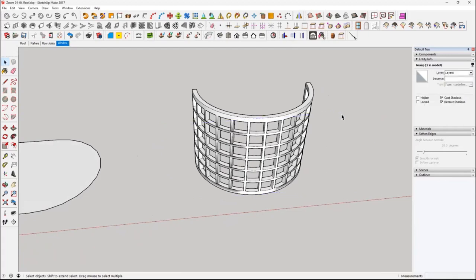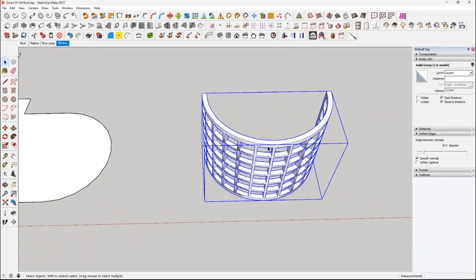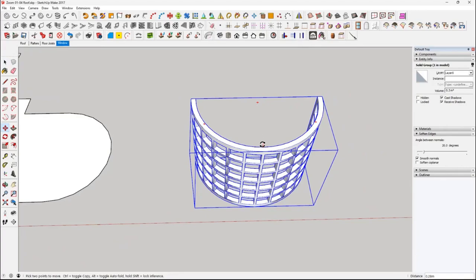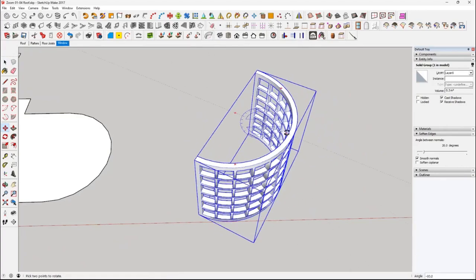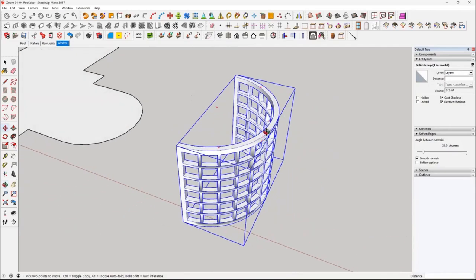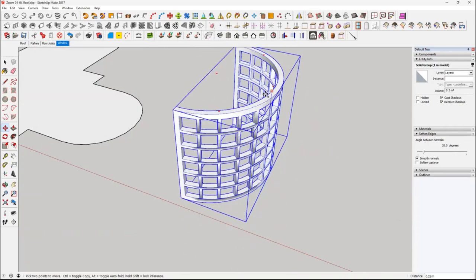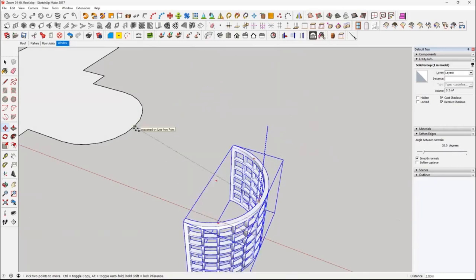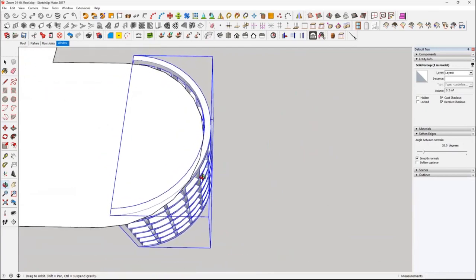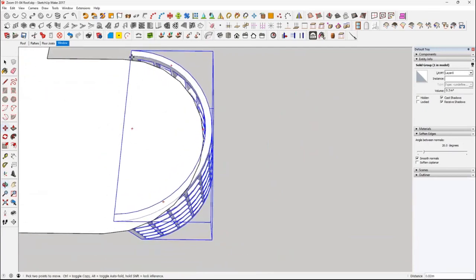The frame bit, you can click on and delete. We don't need it. So on the window, we need to rotate it and put it on here. So if we click on the move tool, if you look on the top, you'll get the plus signs. Now you can move it, but also you can rotate it by using one of the plus signs. Click on and bring your protractor up, bring it round, and if you look at the angle, 0, there we go, we've rotated it. Now what I need to do is put this on the front of the building, find the middle, press the up arrow, so we're moving it up now, and then find the middle of the building there, and then press the up arrow again. And we couldn't have got the right one because it's moved. It's not moved in the right place. Easily sorted. Click on an edge, go on the green axis.